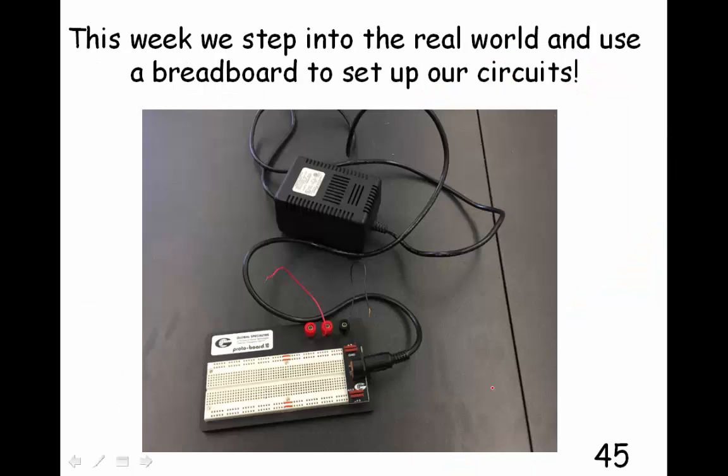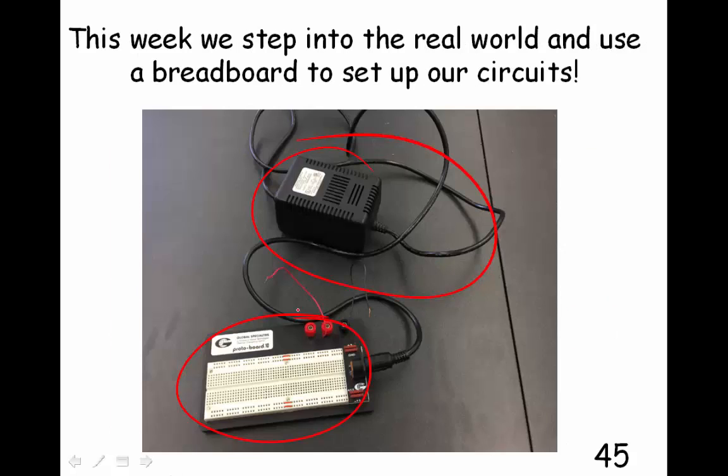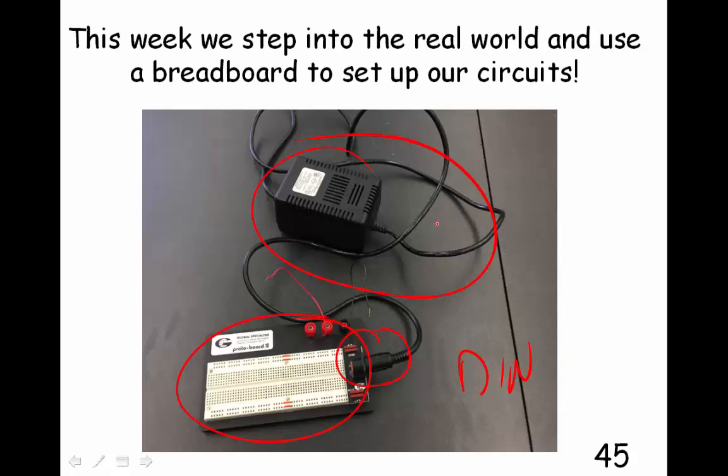Okay, well, let's jump into what we're going to do in lab this week, and this is very important because you have to learn how to use these different materials in our lab. So this is a breadboard, and here's the power supply for our breadboard. When you hook it into this little connector, I think that's called a DIN connector, there are connections underneath here that give us 5 volts from this power supply.